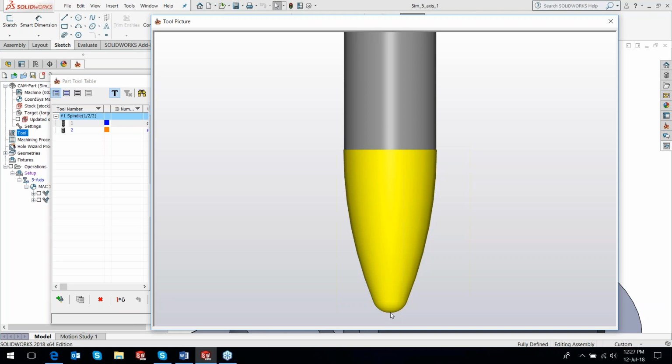So if you get into this situation that you would like to use the maximum amount of your tool's cutting edge, large radius, then it's always better to drop it down to somewhere to this point. You'll still have some uncut area, but that's unavoidable, that you can finish with the further radius of this tool itself. You don't need to have another tool. You could provide a bigger tilt angle and use the front of the tool to finish the remaining area.